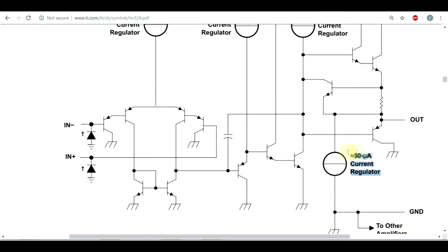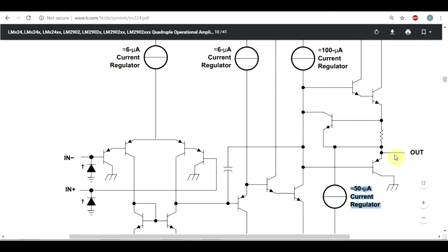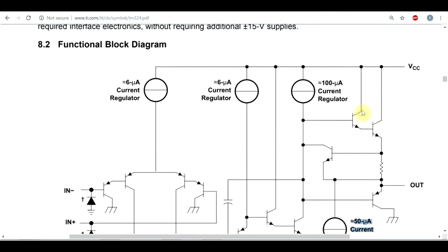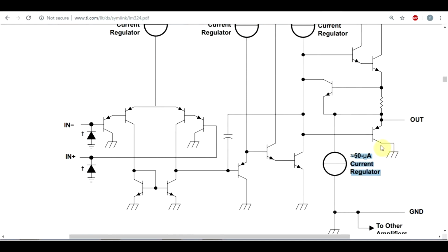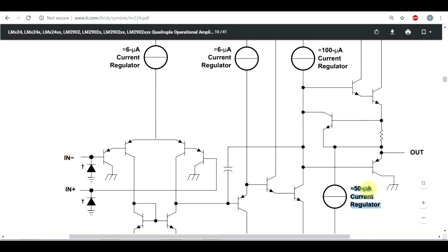We've got a constant current sink on the low side, but on the high side we always have this sort of transistor arrangement. So for very low currents we can go with the output voltage to the negative supply rail, but with the high output swing we are limited by these two transistors. And of course, when much higher currents are needed, then this 50 microamp current regulator steps out and it becomes a proper class B type of output stage.